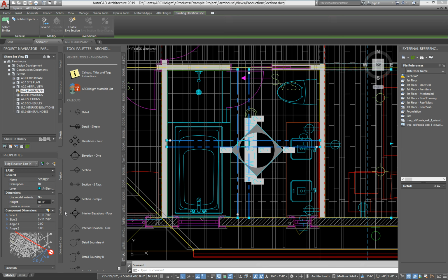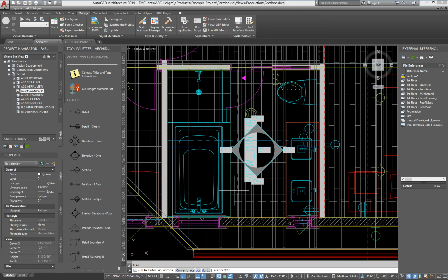So I believe my ceiling in that area is 9 feet, so I'm going to add ½ inch to that. Like that. And then for lower projection, I also want a ½ inch down into my finished floor, so I get the same amount of thickness around the edge. So I'll do ½. All right, and that should do it.